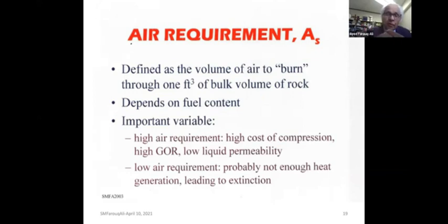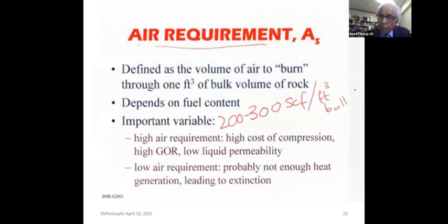The other very important number is air requirement. How much air do you need to burn through 1 cubic foot of rock? It will typically be 200 to 300 SCF per cubic foot bulk volume of rock, or the same number in standard cubic meters per cubic meter of rock bulk.